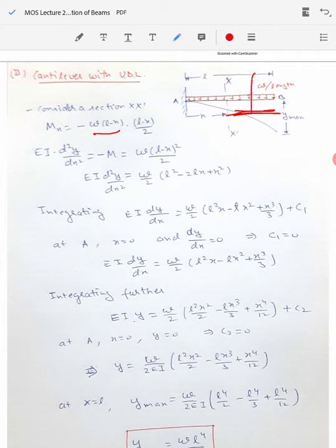As we know, while making the calculation for bending moment and shear force diagram, for the uniformly distributed load we can assume the load to be acting at the middle of the length of the beam for which we are considering it. So that distance will be (L minus x) divided by 2. So the load value W(L minus x) multiplied by (L minus x) by 2 is going to give us the bending moment at section XX dash. We have done this exercise in the case of BMD and SFD. I hope you remember it.